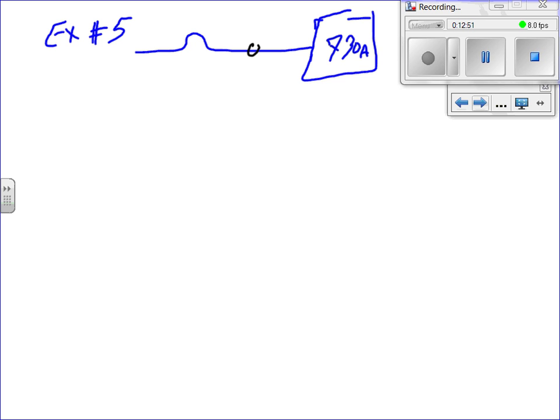And I need to size number 1. I need to size number 2, and guess what? I need also number 3. Can you guys see that we're following the same rhythm? We don't want to switch gears, otherwise we just keep going the same thing over and over in different angles. 730 amp piece of equipment, and we need to size for this piece of equipment. Okay, it's continuous, by the way.